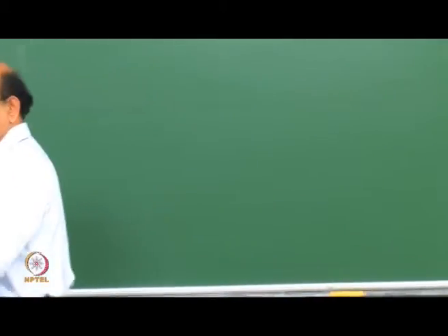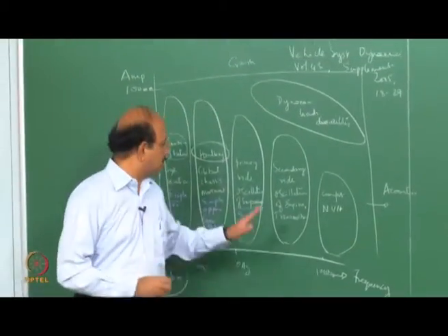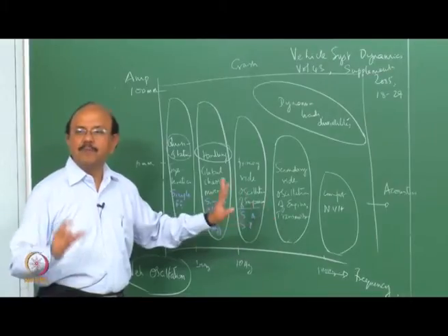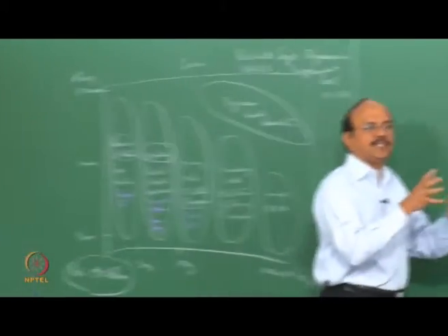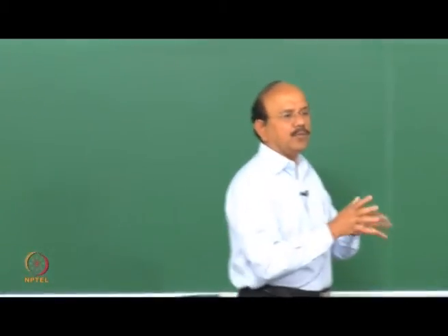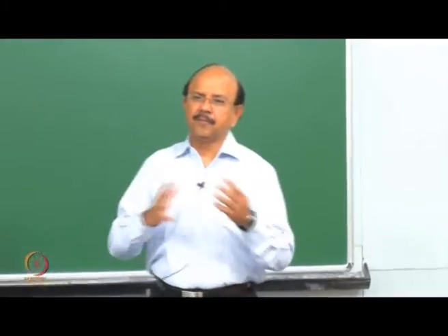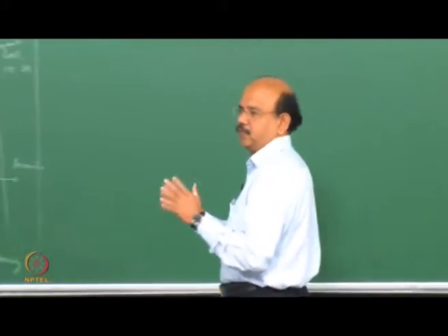Ride usually is divided into two categories. One is what is called the primary ride, and the other is what is called secondary ride, purely in terms of the frequencies. The lower frequencies at 10, 12 hertz, you would call this a primary ride. People vary when they define exactly what the primary ride frequency is.